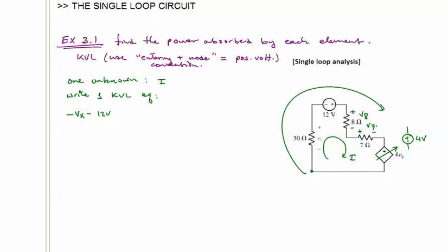The reason I'm going to do that is if I define it this way, I can say V8 is equal to 8 ohms times I. So I have used the passive sign convention, where if I have a positive current I entering into the positive terminal of V8, then the VI relationship is V equals RI rather than V equals minus RI, which we could work with, but it would be confusing and prone to error because we would probably lose the sign at some point.